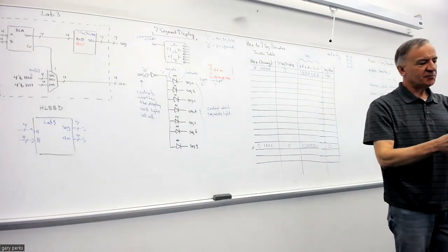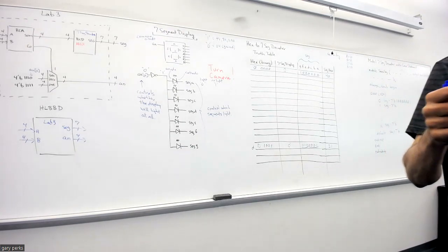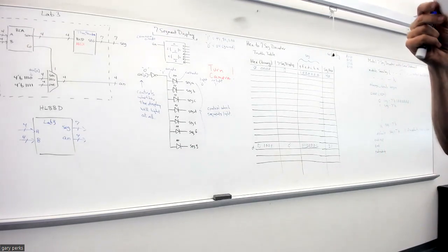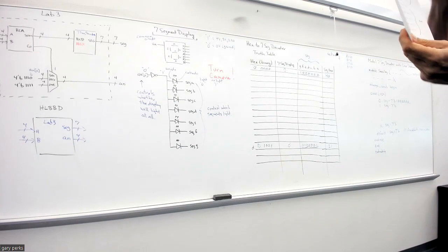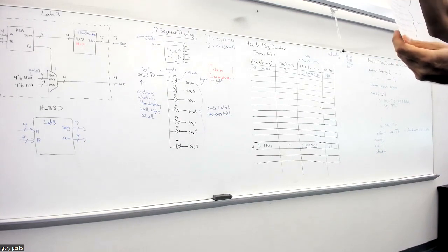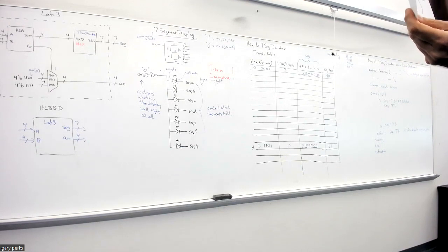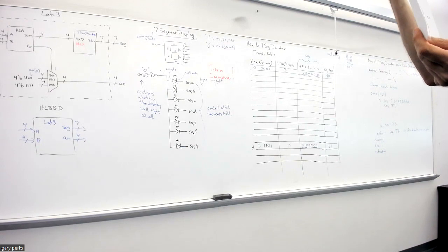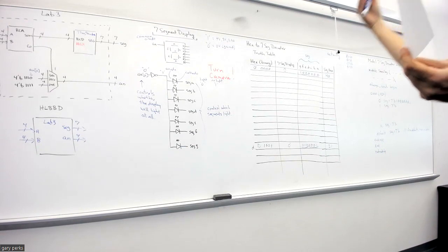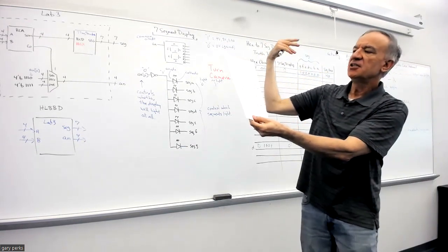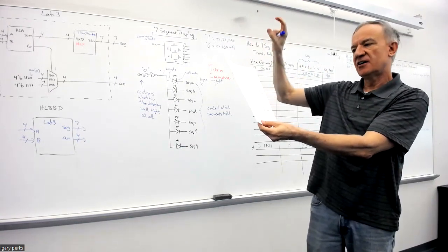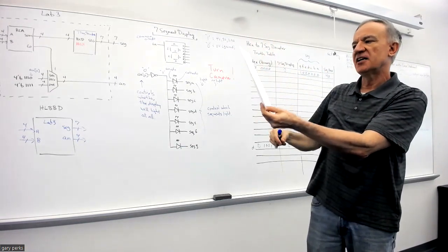When you look at the constraints file, you're going to see that there's a whole section for the 7-segment display. It says segment display. And you have to, what we call map, whatever you called your segment bits to the segments that are on the Basys board as part of a display.